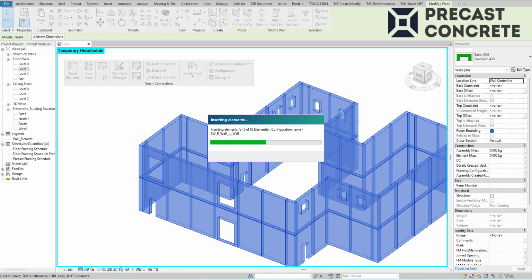What I've done is I've set that these families will be placed from certain wall edges, from a certain front wall face, and other positions where I want to place different families. Approximately it will be like 30 families implemented into one wall element. And I don't need to create any views or adjust the camera view to have these elements placed automatically, or to copy those families from one wall element to another, and so on and so on.